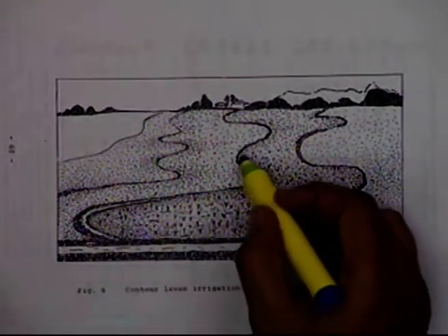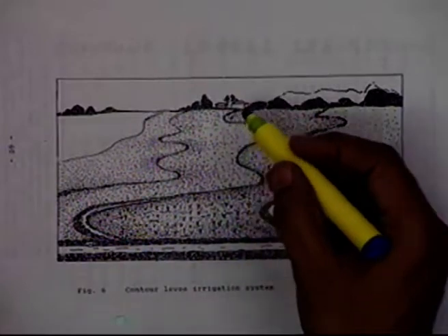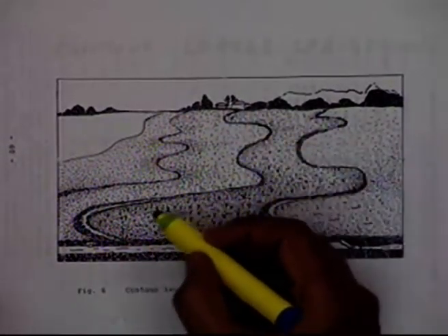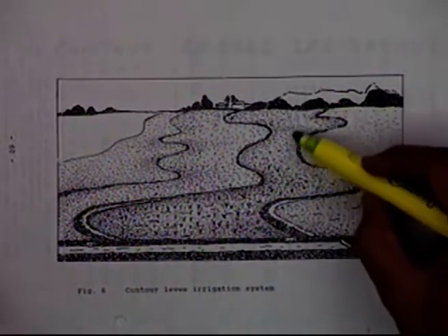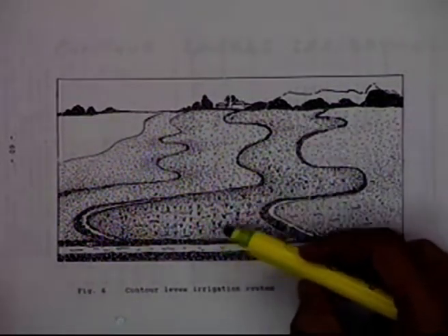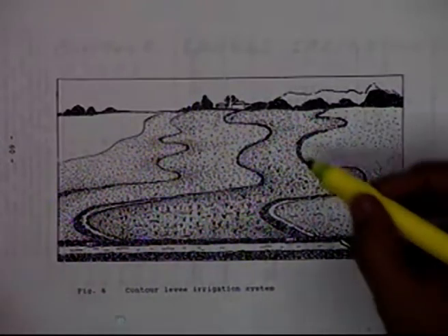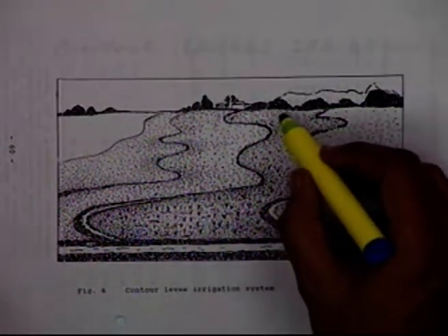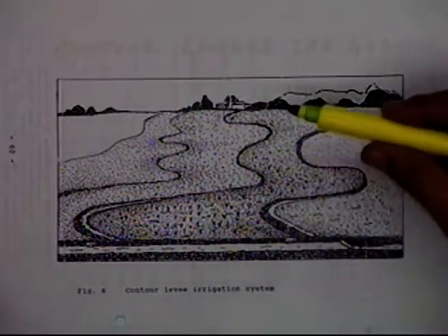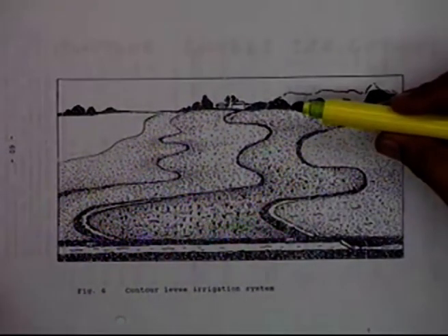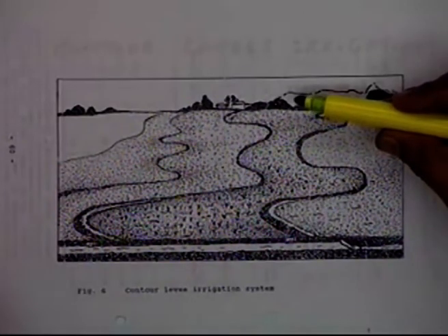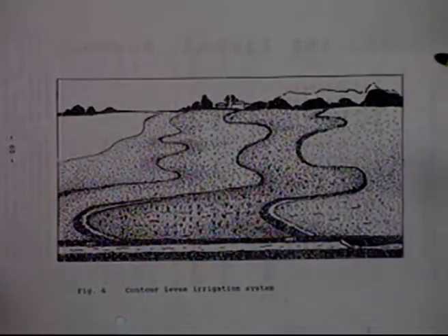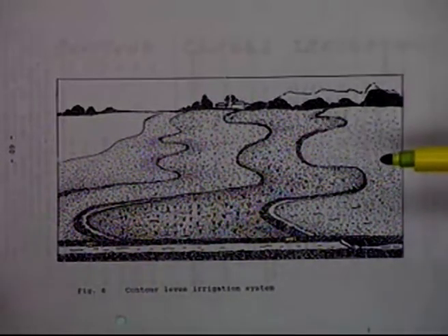These are the natural contours which might be having some downslope, because unless the slope is there, you might find that the water might not move in the longitudinal direction. So you have to have some slight slope, otherwise the stream size will have to be very excessive. The lesser the slope, to cover a larger area you will have to have an excessive stream size, but that can only happen if the soil type is conducive to those higher stream sizes.